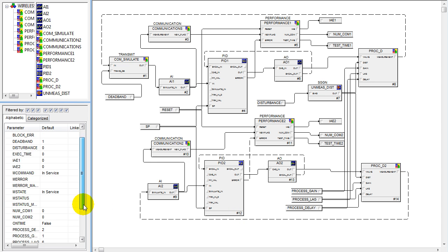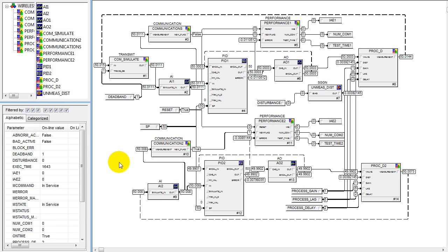For the simulation, you will notice that the simulation contains a dead time of 2 seconds, a time constant of 6, and a gain of 1. Therefore, for the reset, we're using 8 seconds in the PID as well as in the PID Plus.